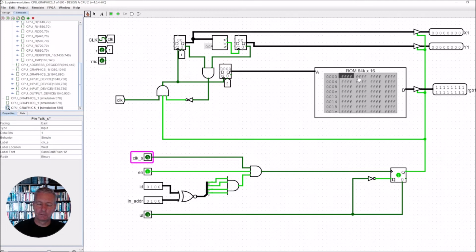But in order to get it on the display, remember the display is going to be 256 values in the X direction. So we're going to count 256 for X. And then when it gets back to 0 again, we add 1 on to the value of Y. And then count 256 for X, and 1 on for Y, and 256 for X, and 1 for Y. So it means that we're going to run along like this, and then down, and along, and down, and continually add each line in order to create the whole image on the screen.